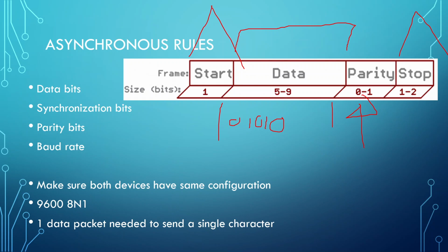And what parity is, we have 2 versions of parity. This is also where it gets confusing. We have even parity and we have odd parity. All right. Even parity, we're going to add 1 digit here. So parity adds a spot right here. And basically, the goal of even parity is to make the value of the data plus the parity bit even.